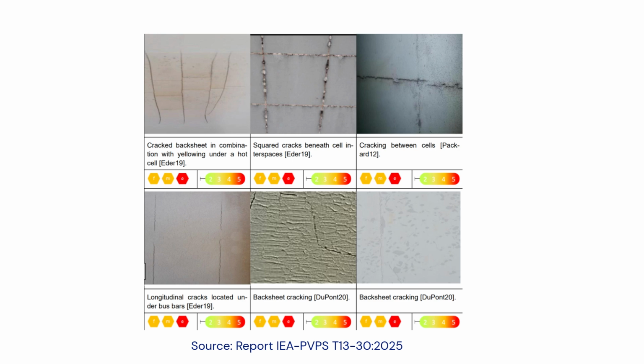On the long term, power degradation due to the penetration of moisture into the module, which induces further failures, like corrosion, delamination, can occur. In the case of deep cracks reaching the active part of the cells, the insulation is immediately compromised and safety is not anymore fulfilled.